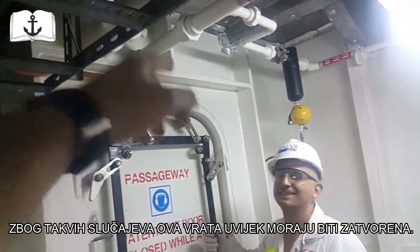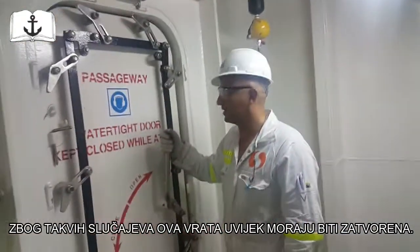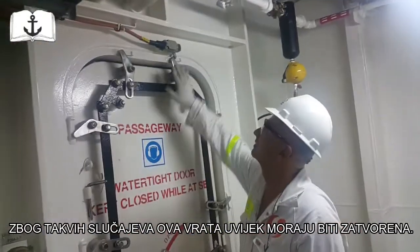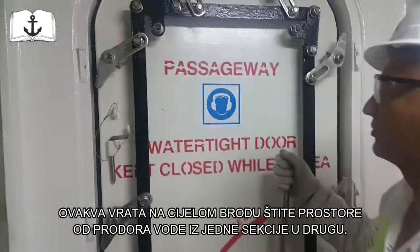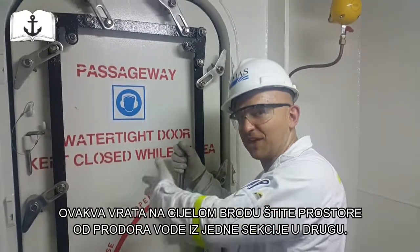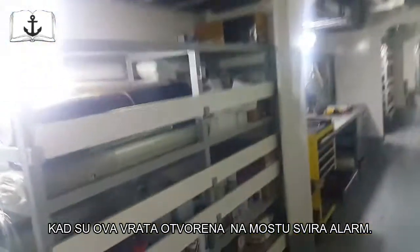This is why you have these thingies. These doors need to be closed. It's a watertight door. Exactly, but there is a sensor up there, and this is why they need to be closed. This is according to the rules, so that if we flood the room, we have the redundancy and we will not flood the rest. Exactly, it will not flood the rest. When this is open, there is an alarm on the bridge. Yes.